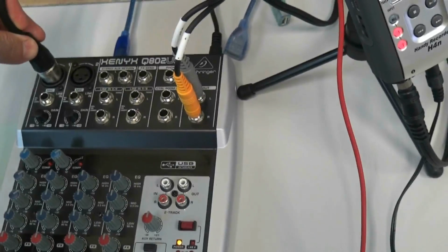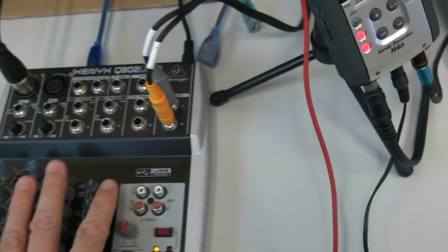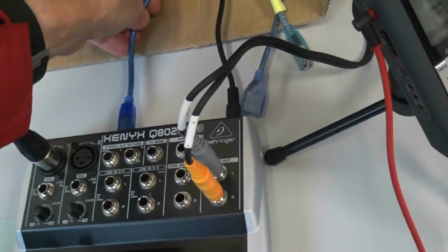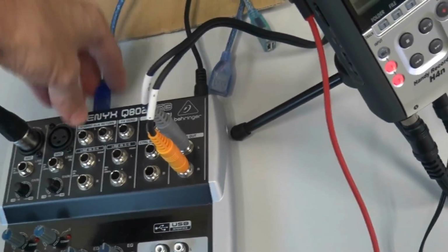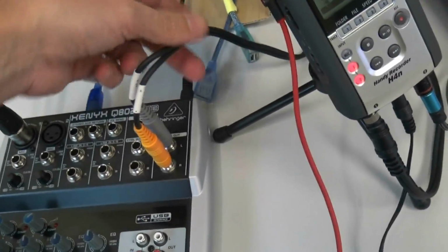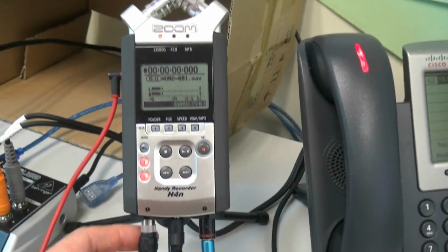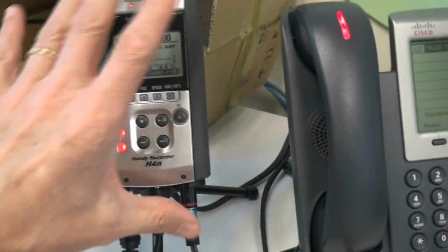So what about the first channel? The first channel is actually coming out of the mixer here. Let's have a look at this again. We've got the Rode microphone bringing the signal into the mixer in the first channel. The mixer is sending out that signal in 2 ways. Number one, it's sending it to the computer, so the person you are Skyping with is getting this signal through the USB, and that's my voice. It's also sending out a signal through this main out, which is coming all the way through to this first channel of my Zoom recorder. So this is what enables me to record separate from the computer.